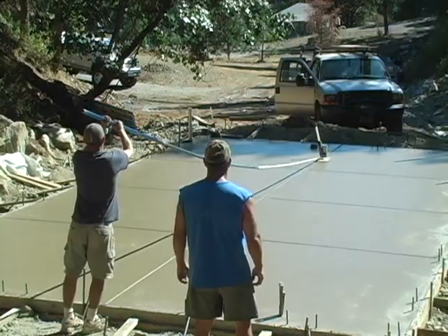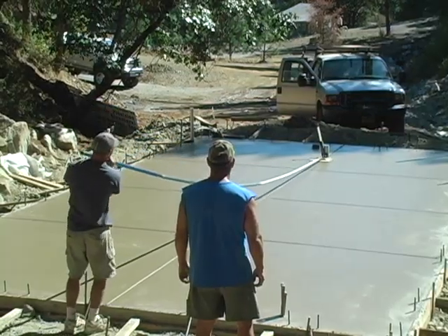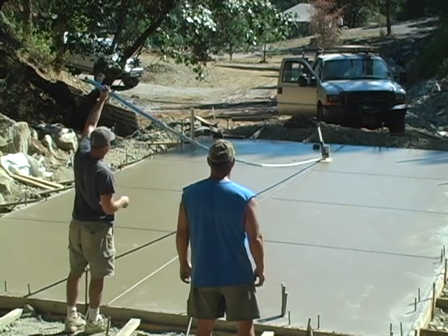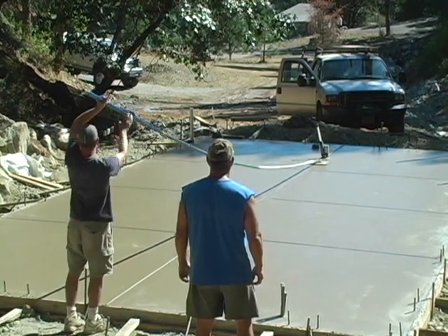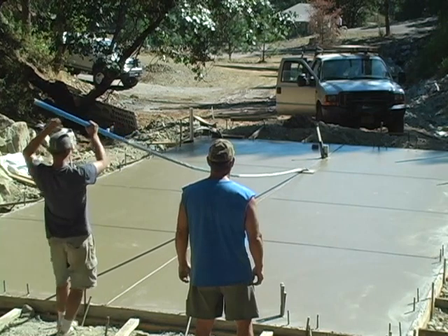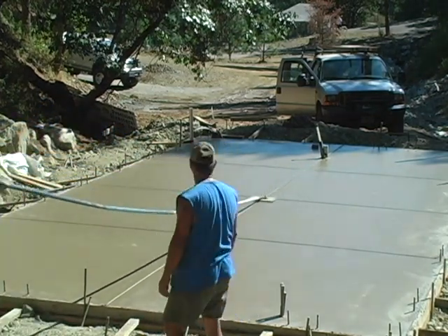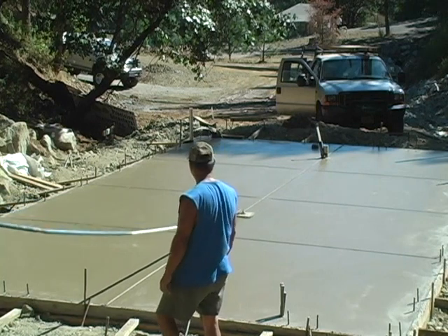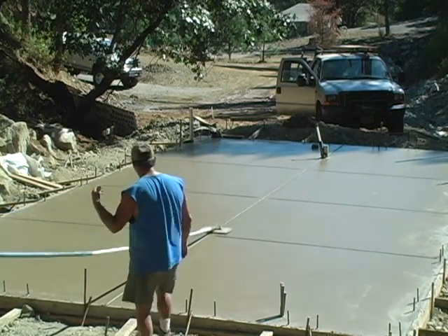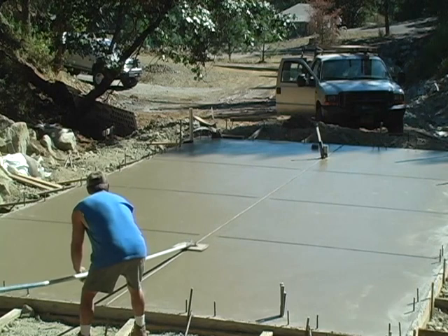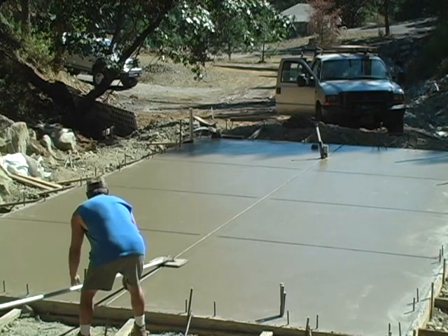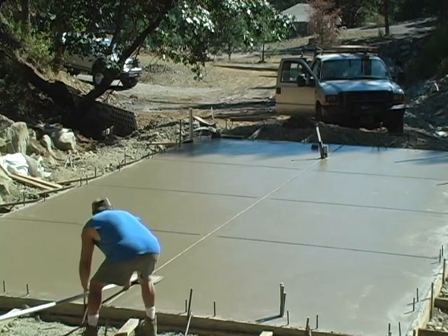The final pull on the long groove we've got here, now we're trying to clean this last groove out. It's the last pull we'll do all the way through. You have to have a second person there to help you get the grooving plate off of the surface of the concrete, because with this much extension pull, there's no way you'll be able to lift it and maintain that angle. So you see as we get right to the edge here with the grooving plate, the second guy will lift it off at the end.